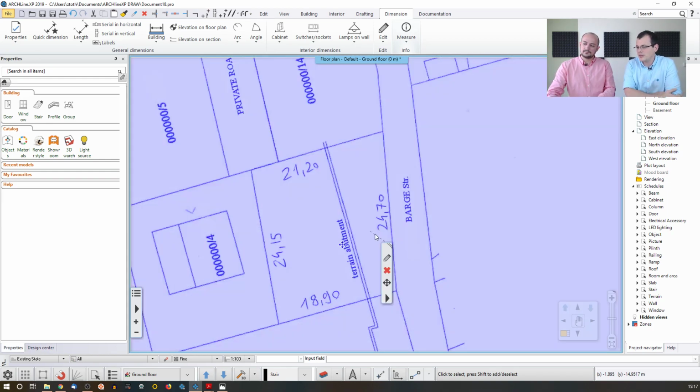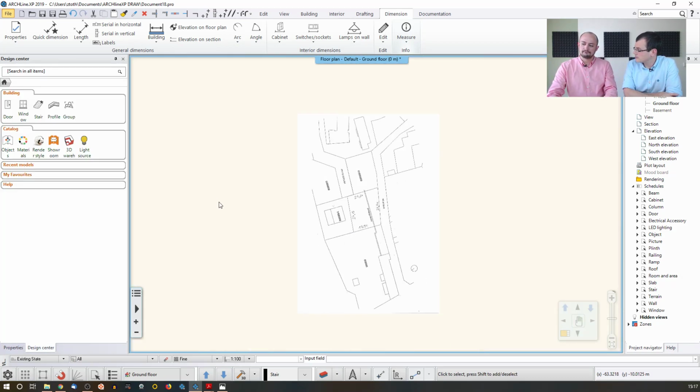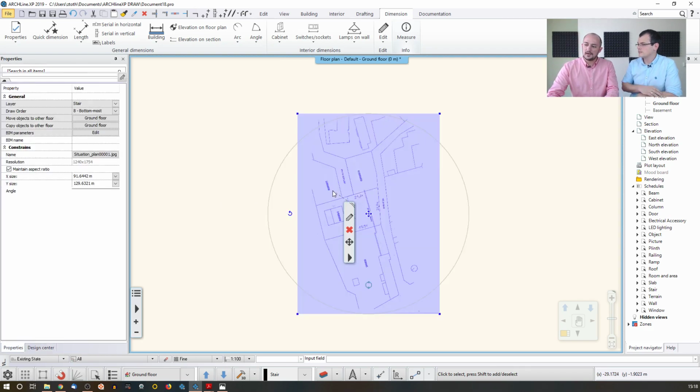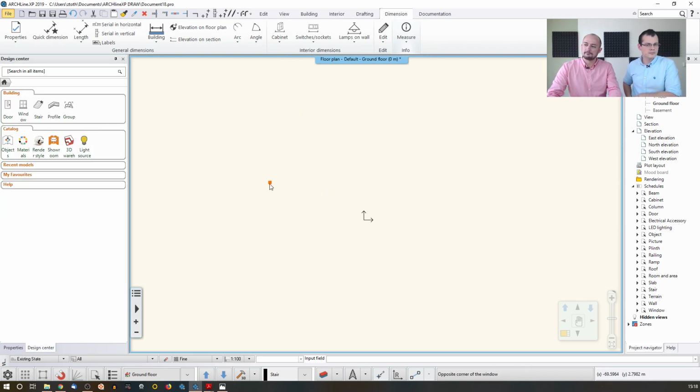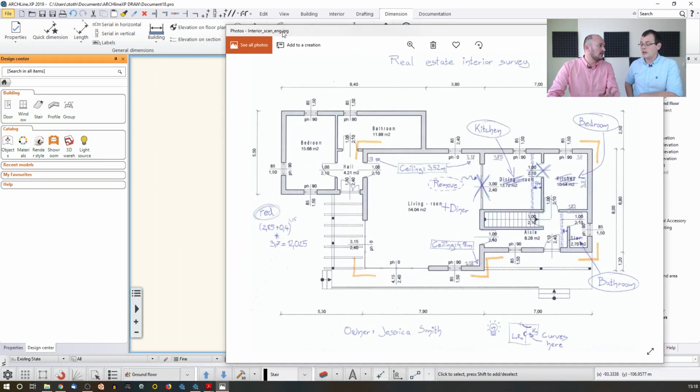So much about images. What happens with CAD files, DWG, DXF? How do we import those? Well, let me just mention that this would have happened if I worked with a classic JPEG file. It would be imported exactly the same. So if I import this, I measure this content, and then I can work on top of that. In that case, I won't use the walls from the DWG. I will just literally click through, type the distances, and draw the walls on top of the image file.